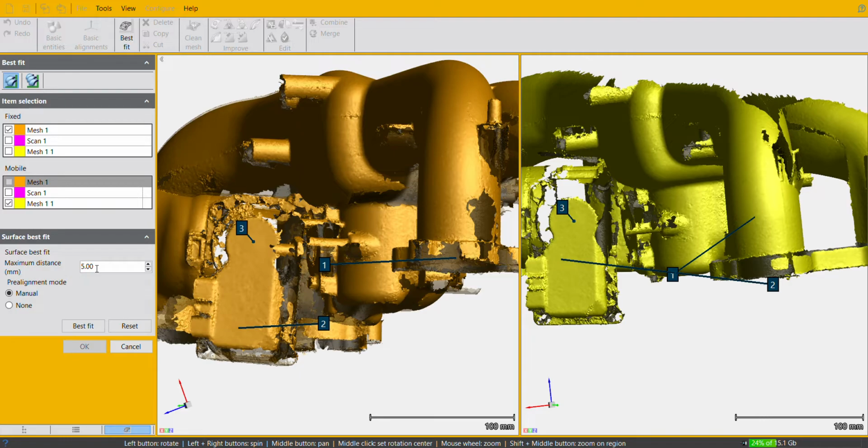This has come in handy as a control tolerance when you do things that are large surfaces, like bumpers, for instance. I've done noses of cars where you have the main scan, you had to get the bumper in two different scans, and you align those, and then you're trying to align it to the front of the car so you can fit a front mount intercooler, for instance. What they used to call align is now best fit.